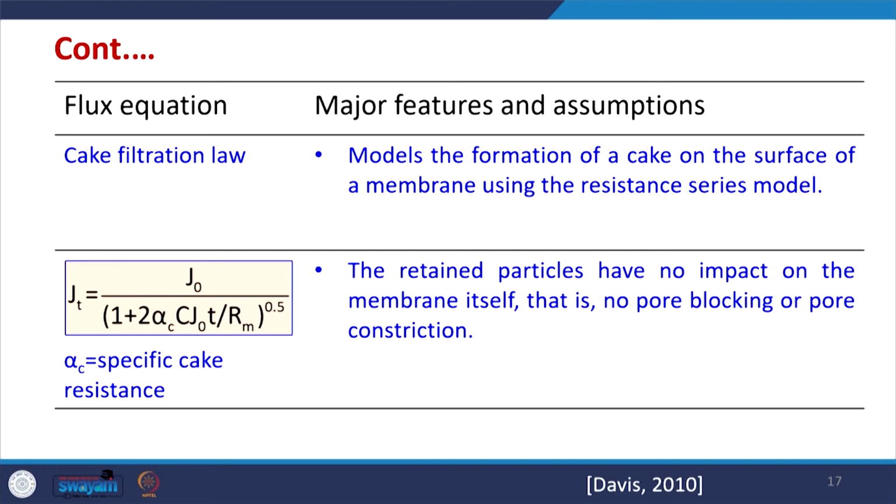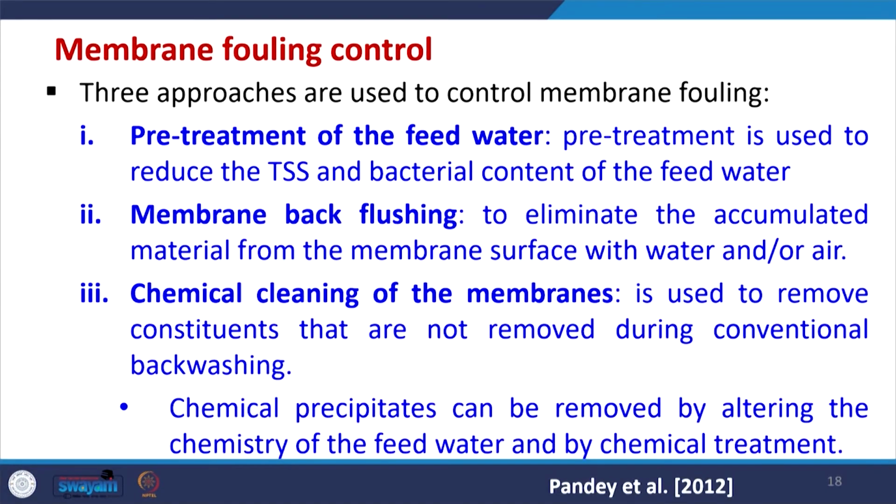Then we have a cake filtration law. Under this cake filtration law, the formation of cake on the surface of the membrane using the resistance series model is assumed. So, this is the type of equation. The retained particles have no impact on the membrane itself, that is, no pore blocking or pore constriction is assumed. So, these are the different models and other modeling approaches.